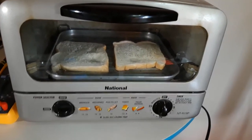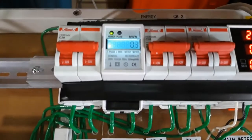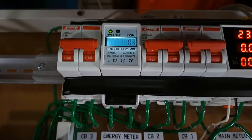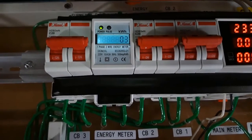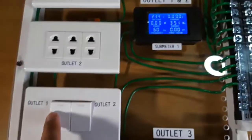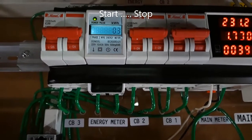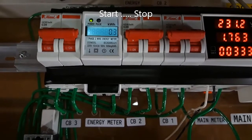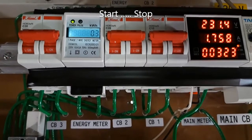For this demonstration, let's connect a 400 watt oven to our test board here, and this one is connected to the energy meter. For now, let's start the oven and just observe first what will happen to the energy meter. As you can see, the LED pulse lit up once, and we will synchronize the start of the Hioki clamp meter at that pulse and stop at the next pulse.